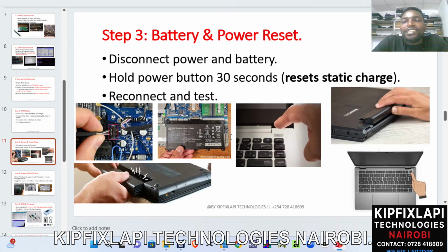You try as if you are trying to power on your laptop, but at this stage, you don't have any power plugged in. That is meant for resetting the static charges. After you've reset your motherboard, you put back all the power. That is, you connect back the battery and even the charger. Then try to power it on again.